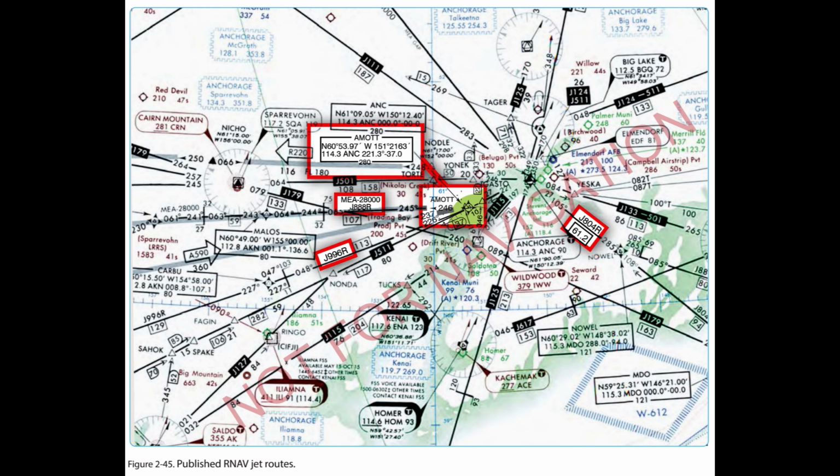An operational service volume has been established for each class in which adequate signal coverage and frequency protection can be assured. To facilitate use of VOR, VORTAC, or TACAN aids, consistent with their operational service volume limits, pilot use of such aids for defining a direct route of flight in controlled airspace should not exceed the following. 1. Operations above FL 450 use nav aids not more than 200 nm apart. These aids are depicted on en route high altitude charts.